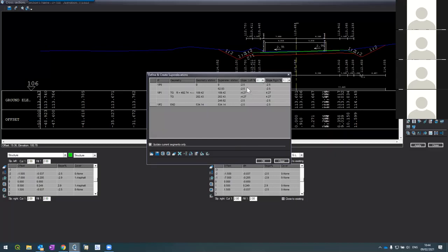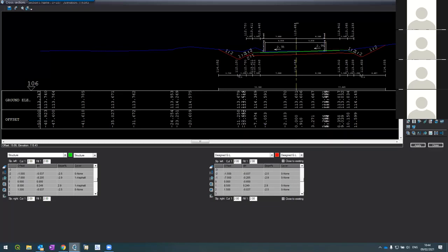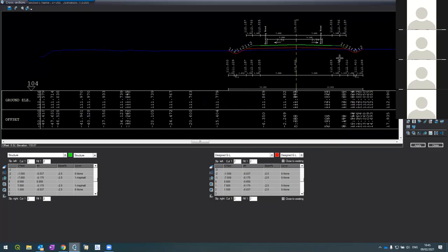So I tell her, in this case, you have to take the suggestion in the software, copy, go to -2, press OK on this one, stand here and press paste, because the 2 lanes are following the same. In fact, if you want your shoulders to super elevate as well, this is what you will have to do. Again, just practice it and then you'll see it. Other questions, please, but this was a good question.